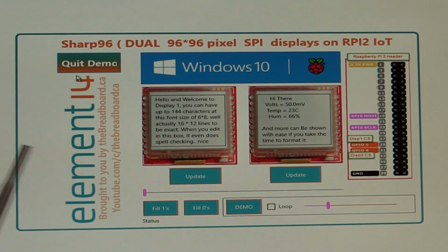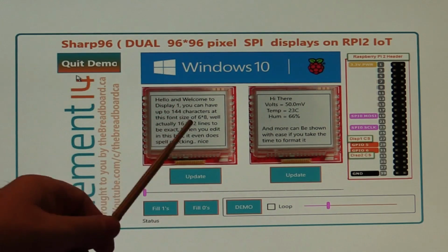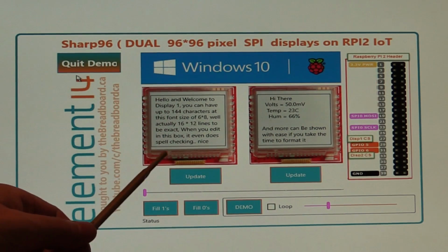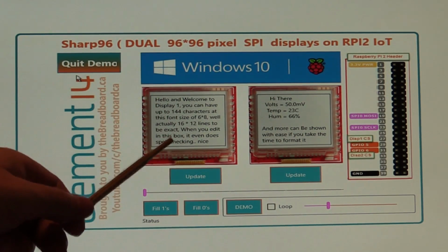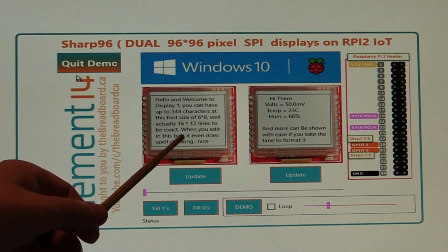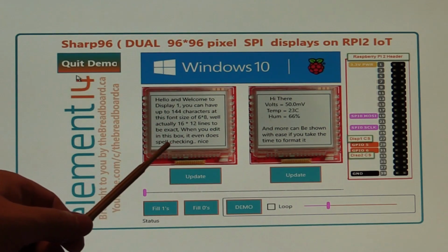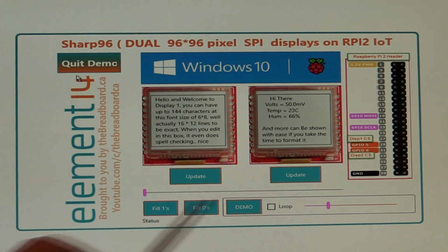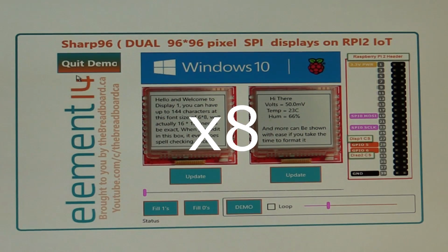The other thing I've got here is a bunch of the different functions that are available, things like line draw, circle, rectangle, and I can actually write to the matrix fonts as well. I've only got a single font as far as an array is concerned, which is an 8x6 font, but you can scale it up by sliding this big slider anything up to ×9, which basically gives you about 1.5 characters on the display if you do it that size.